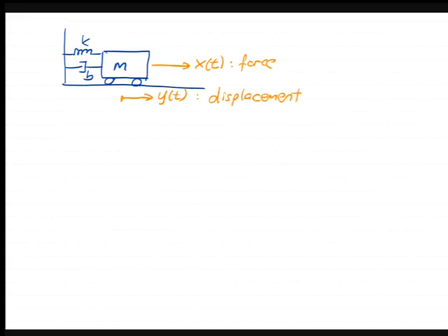All right. So in this case, just like we pick inductor currents and capacitor voltages for circuits, for these types of mechanical things, you usually select positions and velocities to be the state variables. So I can choose y to be z1, and z2 would be its derivative. So that's the speed. So d by dt z1 of t is z2 of t, which is velocity.